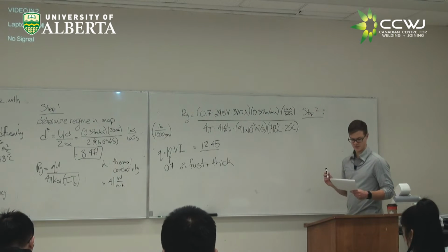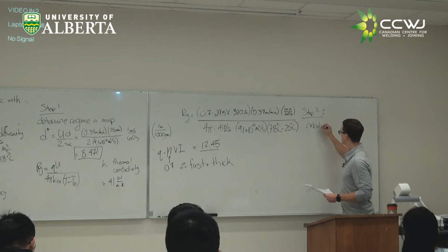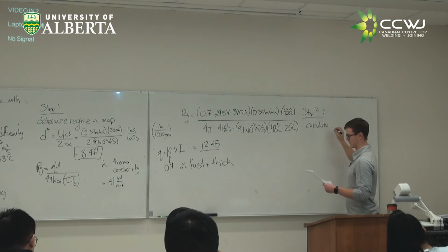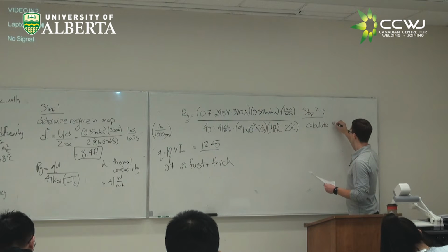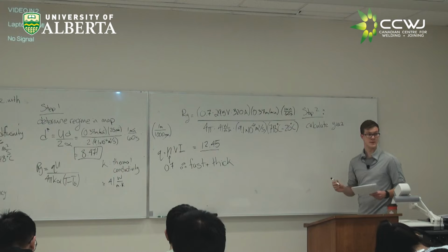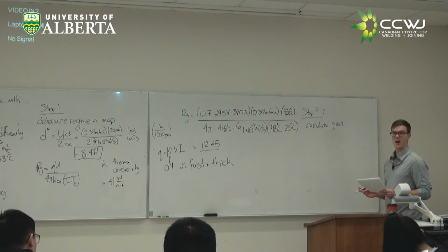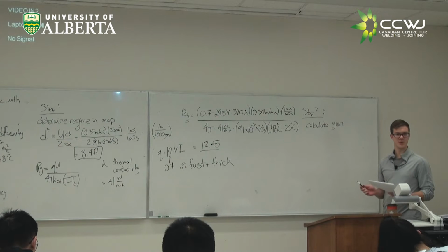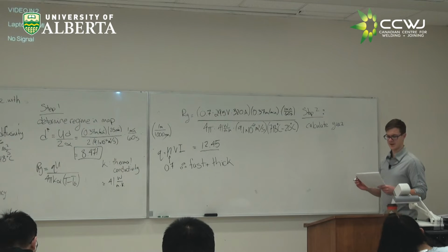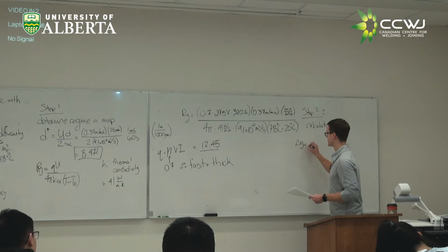So, step 2. We're going to calculate the heat affected zone width. If we're in the fast and thick regime, on the exam you would have these equations in your formula sheet, but today you have them in the class notes. Does anyone have the equation for delta Y heat affected zone for the fast thick regime?